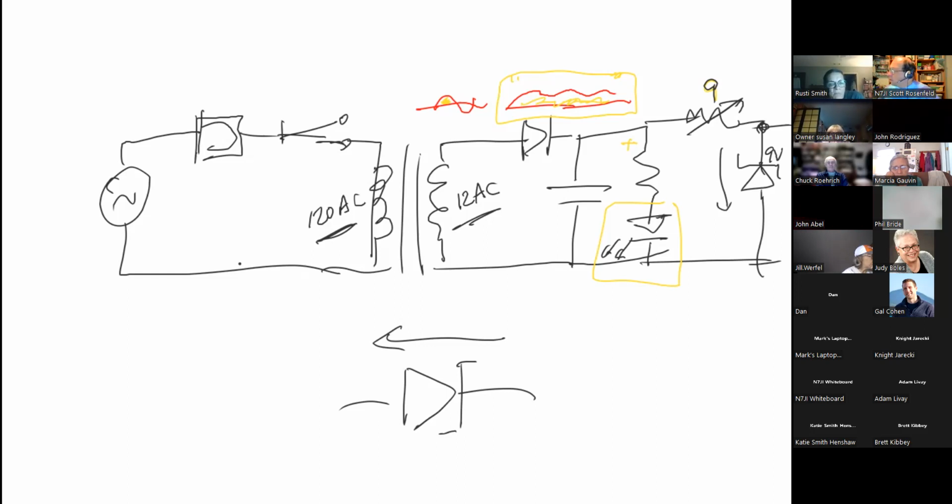So essentially, when there's voltage above it, it takes everything above that voltage and wipes it out. So let's say this is the ripple voltage coming in. It says, okay, I'll work, but your voltage isn't going to go any higher than that. So anything above, this is all wiped out. And what do you have? You have nice, clean DC voltage. This is known as a DC power supply.